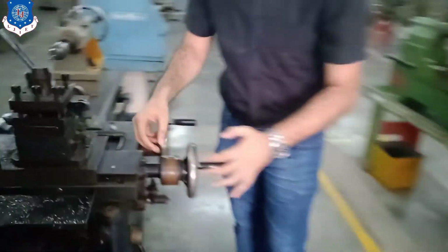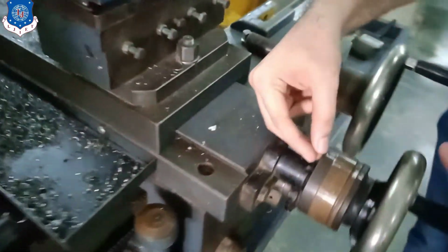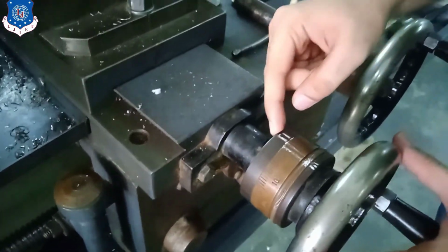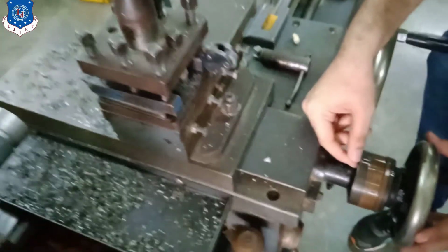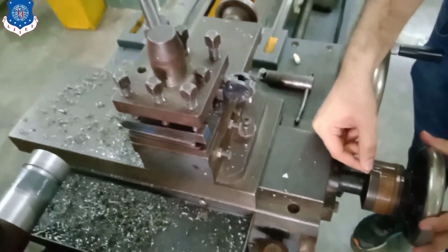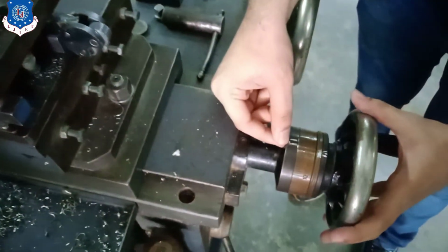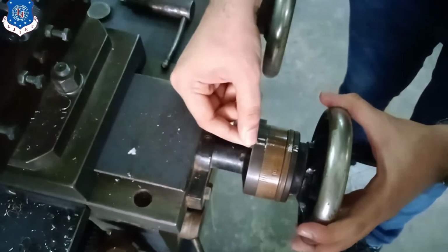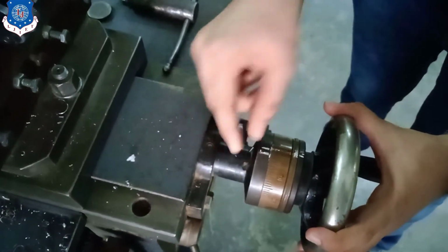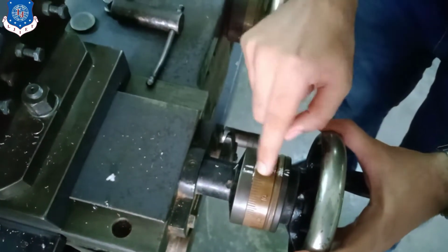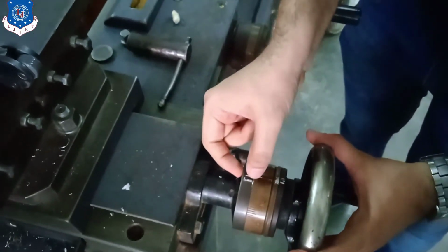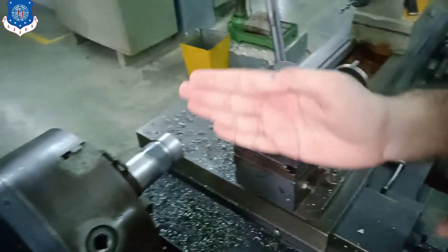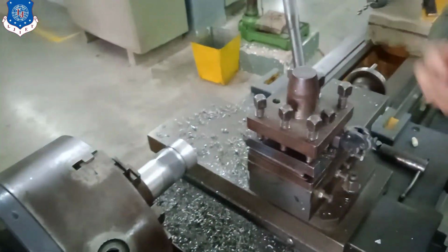There is a dial over here and there is a marking over here. This is our reference point. Whenever your tool first touches your specimen, at that time the dial is at this position. So after each and every pass we will be moving the dial from 2 to 5 portion, 2 marks in each and every step. So by increasing to 2, it will go inside by 2 parts and then it will do the threading. Once again it will come back.